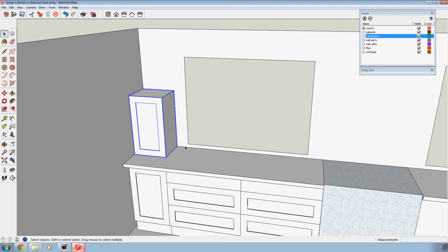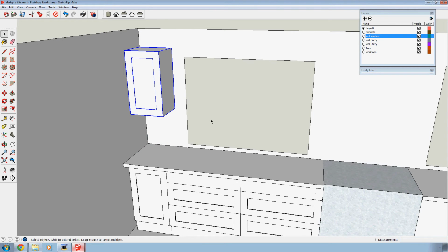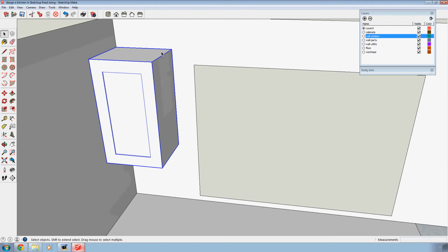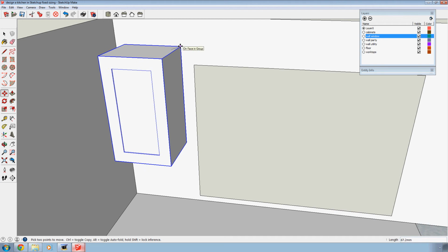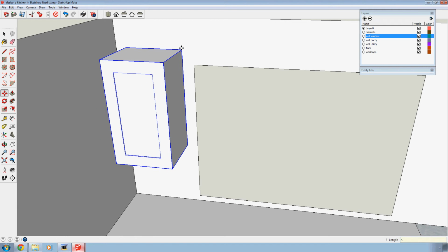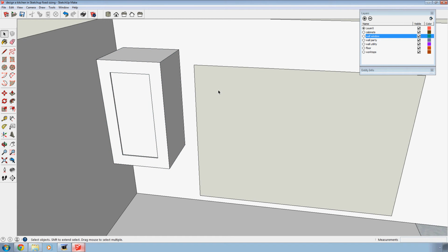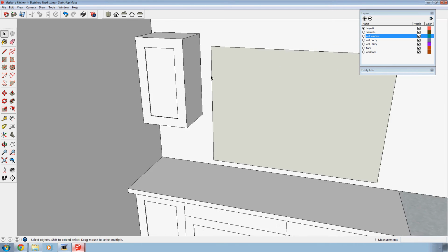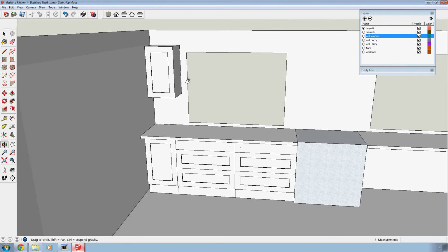Generally I like to have wall units about 500 above the worktop. So I'm going to slide this up by 500. And I also need to move it out 50mm because of the filler needed to get the door opening properly. So move that out by 50. Again, we'll just ask you to imagine that there's a filler in there at the moment.